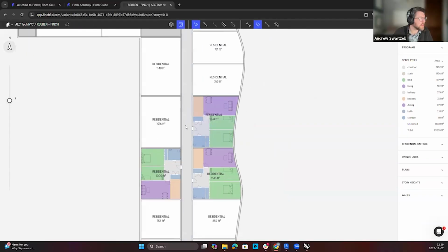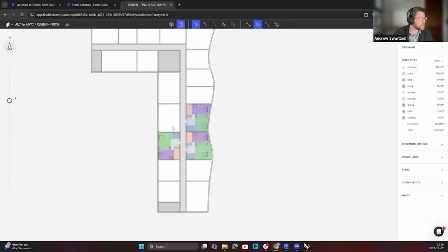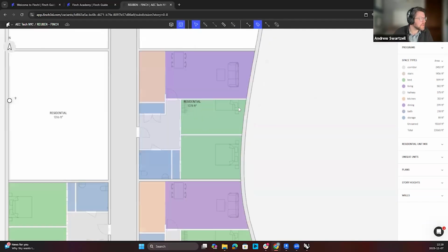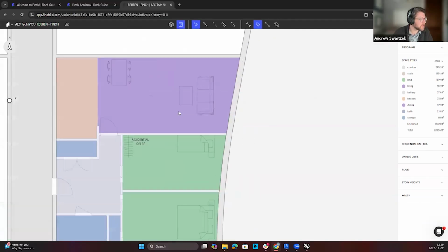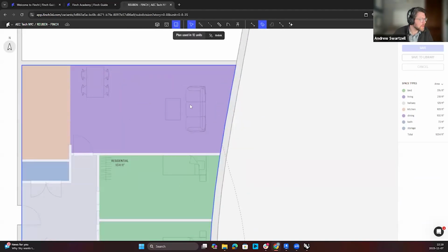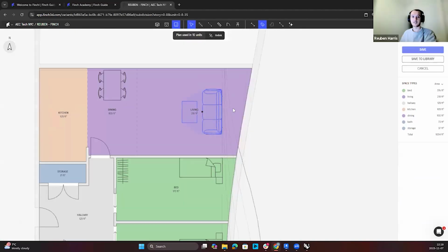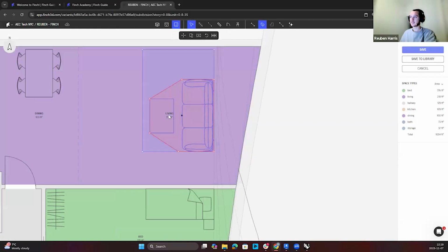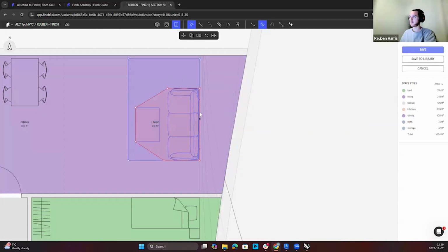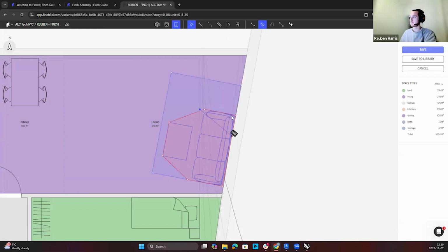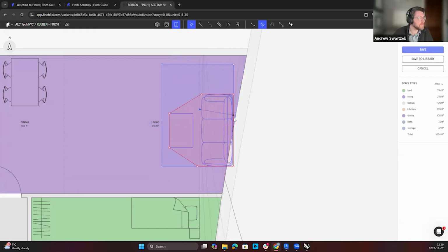And I guess the furniture, whenever you union it, the furniture doesn't move around. You have to move that manually. Is that right? Exactly, yeah. If you select any of the furniture, find the midpoint at the back of the furniture here and drag against any facade, it's going to snap to that facade as well. So you can quickly orient it.